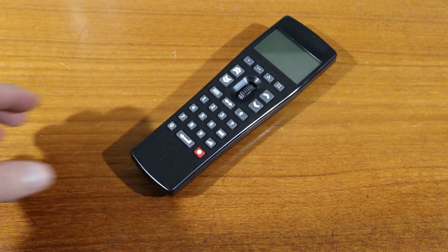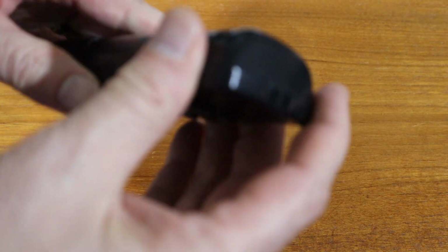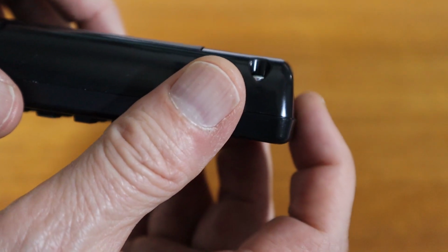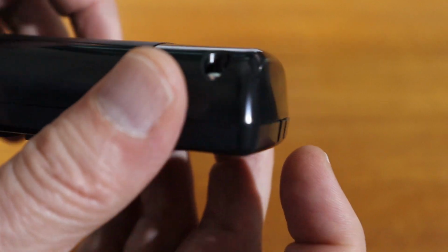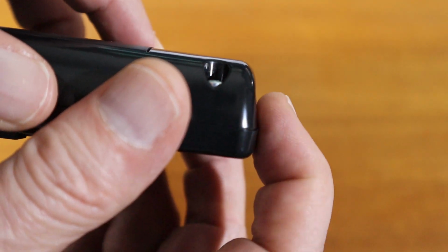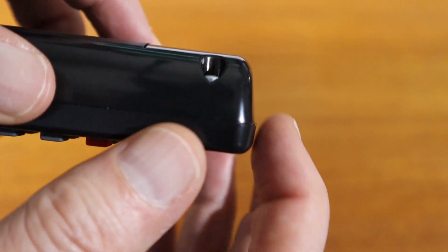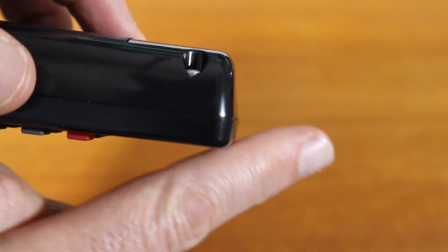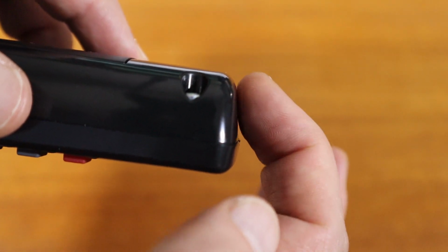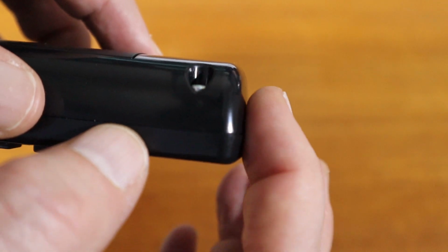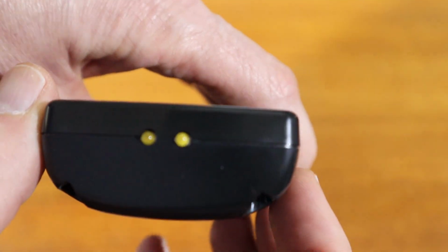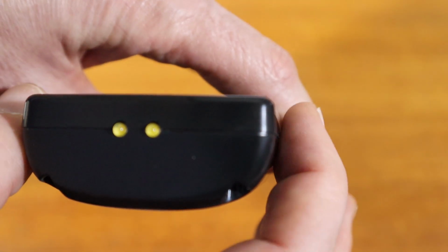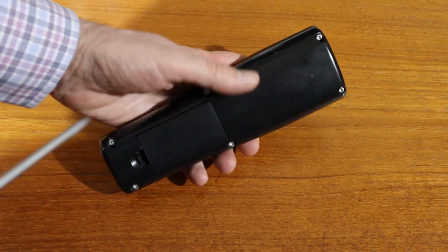But before I do that, there are a couple details I'm going to try to show. One is, if you notice here, the two halves don't line up very well. It's probably a little bit hard to see, but it's about 20 thousandths of an inch further that way for this part than for this part. I'm not sure what caused that. I think it might be shrinkage, because the same thing happens here on the sides. Again, it's probably a little bit hard to see, but I can certainly feel it that way.